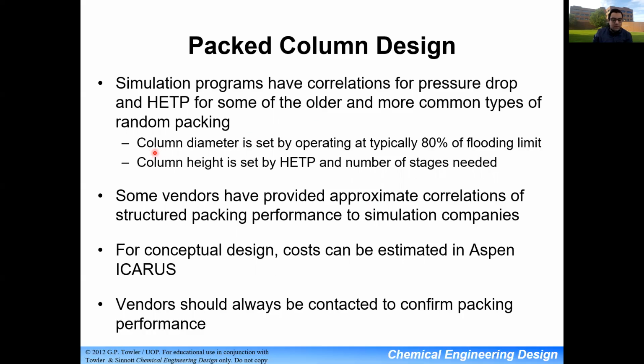And a common thing when dealing with these columns is called flooding. I'm not sure if you're going to deal with flooding in mass transfer, but flooding is when your gas velocity is not high enough to push through the liquid. So the liquid just overflows your entire column and floods it, and your column is basically not doing anything. It's not efficient. There are methods to calculate the flow rate or the point of flooding, and ideally, you want to design the column diameter to minimize flooding.